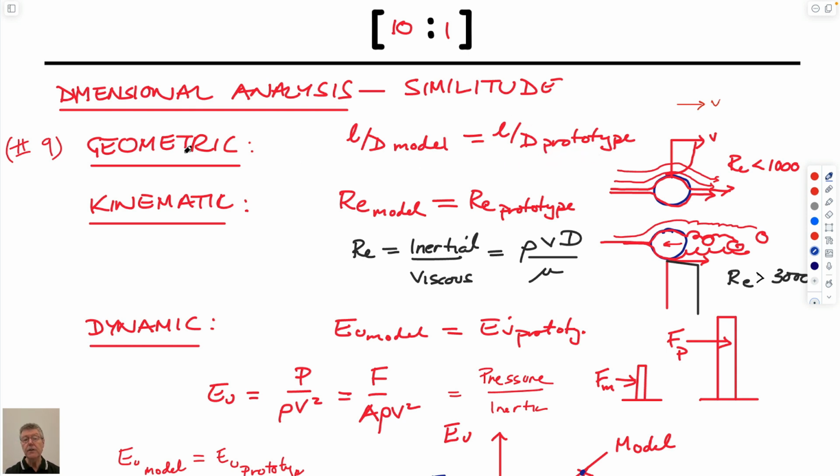And so if you do that, then you have geometric similitude, and your model is a faithful reproduction of your real system. So you have a 777, you shrink it down 100-fold, so instead of being 100 meters long, I'm not sure a plane's that long, but it's a meter long, and every other aspect of it is in similar proportion.